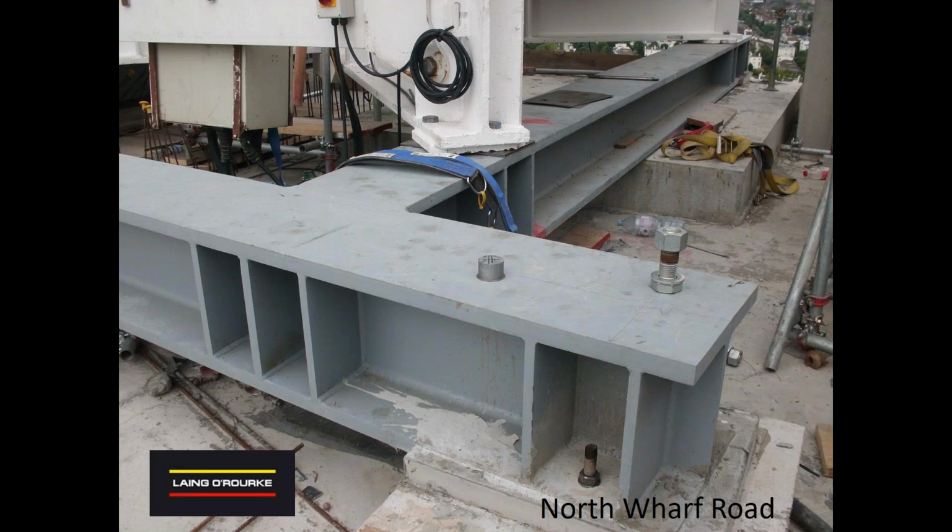The bolt details and the supports are fairly simple. You don't need huge numbers of bolts or huge diameter bolts because you've got the Kentledge, the concrete blocks. The support reactions are high compression, but very little, if any, tension. So the bolts don't have to work as hard as would be the case if you didn't have the Kentledge.